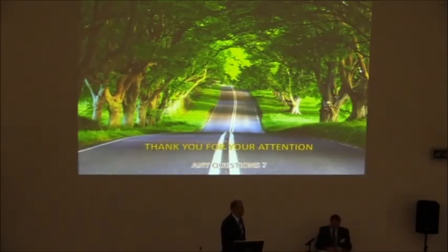Thank you for your presentation. About the quality of the new mix, is it almost the same as the hot mix and the cold mix? For example, can we use it in all countries? We have some very hot countries and cold countries. The asphalt quality is sufficient, right? Yeah. With the stiffness, we got stiffness more than the hot mix. Regarding the water sensitivity, it is more than the hot mix. I have the result for the permanent deformation. It is excellent in permanent deformation. There is no rut depth. Maybe in 2 months, I will start the fatigue. So it is a promising material in the engineering properties.